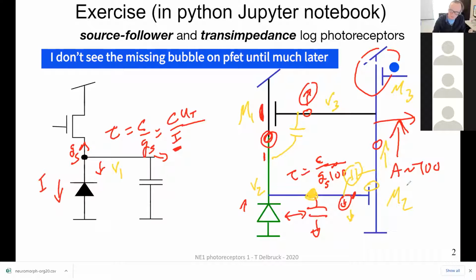Now, the gain of this amplifier on the right, I'm going to tell you this because you need to know it for your exercise. What determines the voltage gain of this amplifier? Remember, in the very beginning of the course, I explained the concept of intrinsic voltage gain, that transistors have a kind of intrinsic voltage gain. For the purpose of the exercise, you're going to have an ideal current source IB. Ideal means it has no drain conductance. It's always exactly IB that's pushing out mathematically, right?